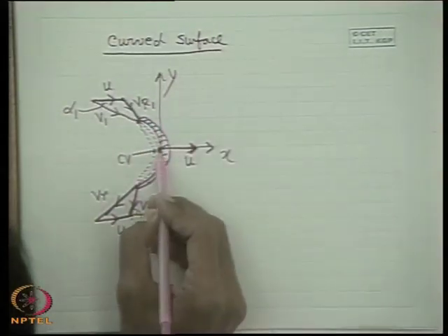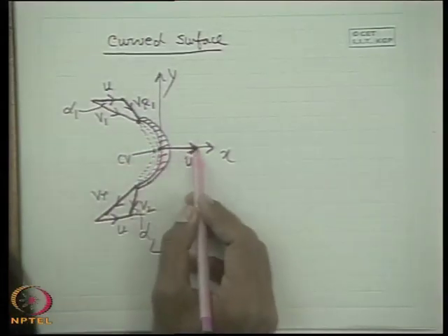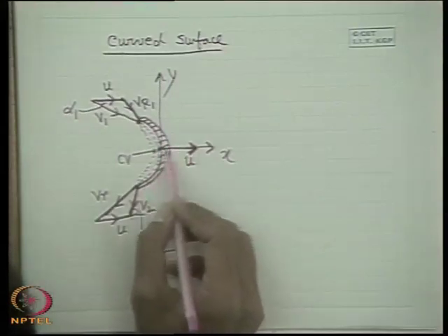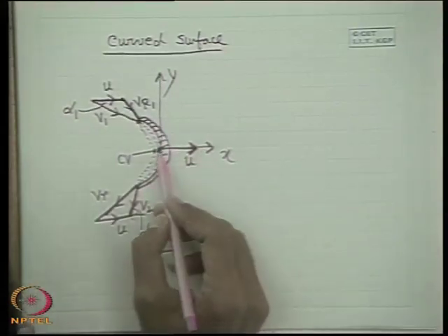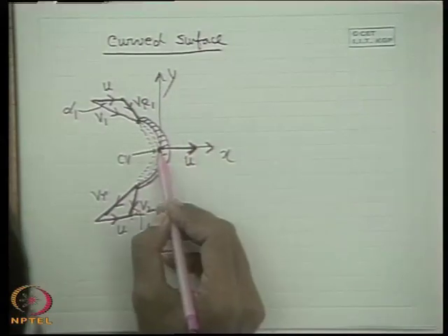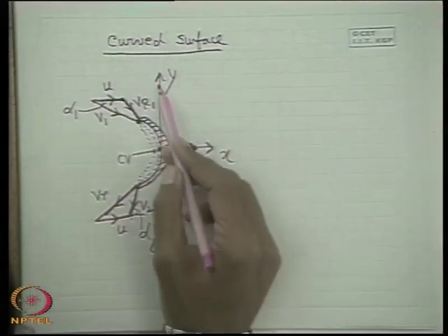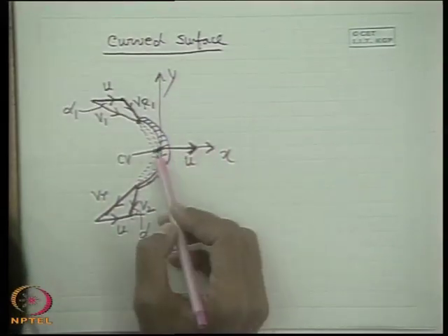So, therefore, we attach the axis with the control volume, and we are taking a moving control volume, moving with uniform speed, because here the system is moving with uniform speed. So, therefore, the axis is moving with uniform speed because it is attached to the control volume, and the analysis will be made similar to the earlier problem with respect to the moving axis or moving control volume.